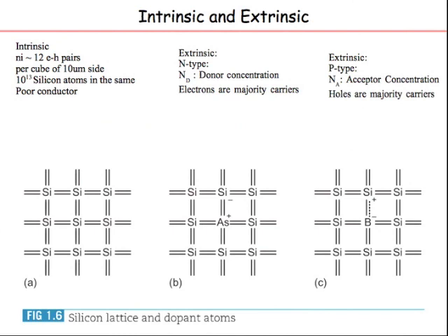So as you know, the transistors are made on a silicon substrate. Basically, silicon has a very nice crystalline structure. Pure silicon, also called intrinsic silicon, doesn't have too many free carriers. Each silicon atom has four valence electrons, so it forms bonds with four other silicon atoms. So it has a nice tetrahedral type crystalline structure, and all the electrons are kind of tied up.